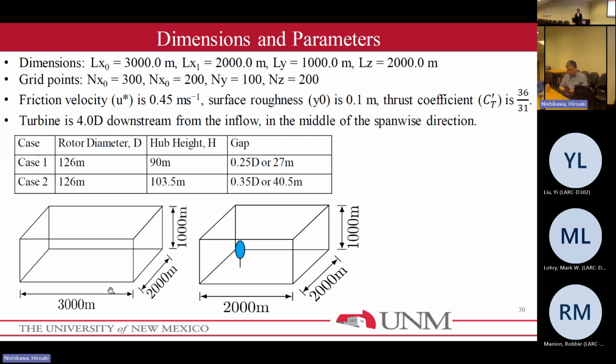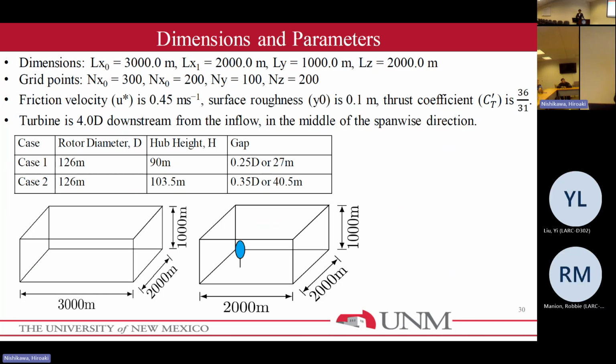I mean, it's impossible to use DNS. Because I saw the name here, DNS. It's not Kolmogorov scale. It's just no turbulence model. Okay. People use RANS actually. Yeah, they actually have coupled RANS and LES, especially for the surface of the turbine. They use RANS there. Yeah. So basically, any CFD code has a DNS capability.